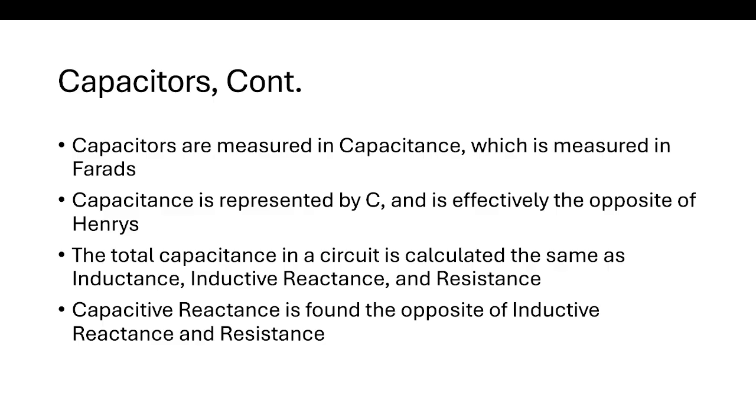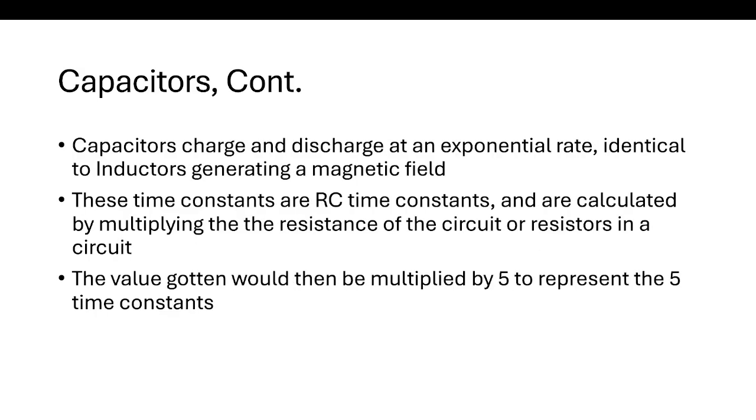So essentially what that's saying is, in a series circuit, you're going to find your capacitance like you would find your resistance in a parallel circuit, and vice versa. You're going to do that inverse addition thing.